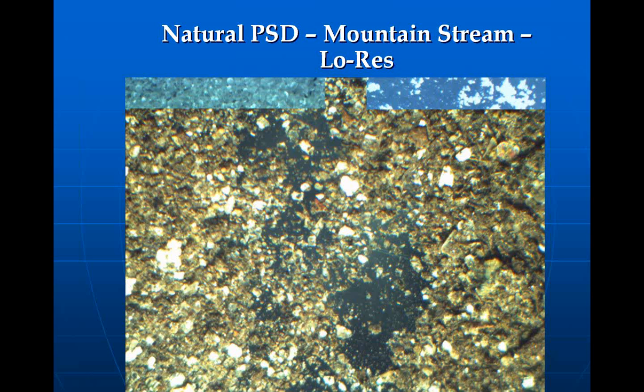And if you saw this as a residual soil, and remember, this stream isn't just carrying residual soils. The residual soils are generally held down pretty well by the undergrowth, forest and grass and that sort of thing. But if you saw it as a residual soil, it would start out as what we might say is a sandy loam on the surface, maybe 40 to 50% sand, maybe 30% silt and 10% or so clay. Maybe a little more silt, a little less clay.